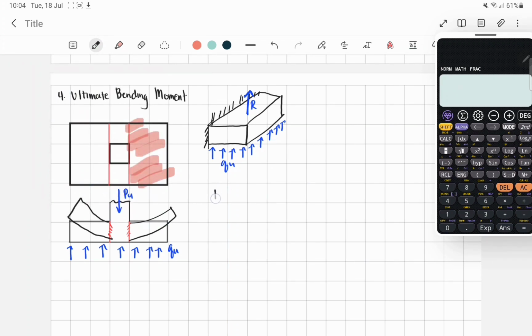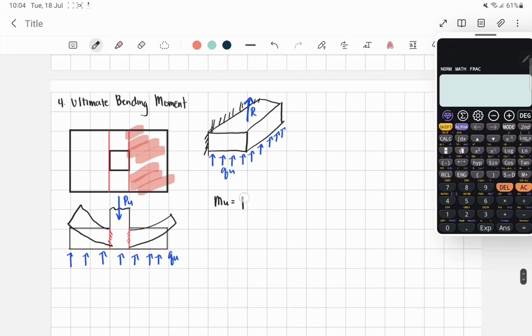Okay? So, to get the moment along that cantilevered beam, force times the moment arm or the lever arm. Tama ba? So, therefore, ganun lang pala kadali to get the ultimate moment. So, F natin, ang force natin dyan, acting on that member is, again, QU, stress times area.